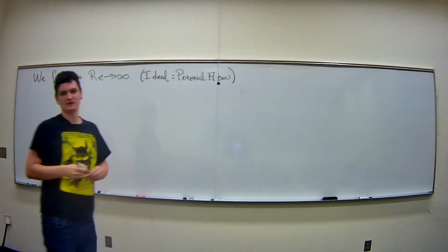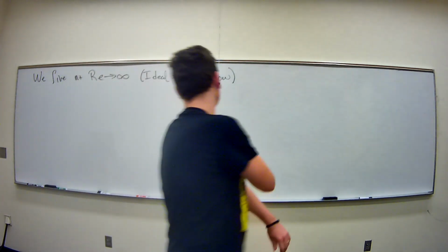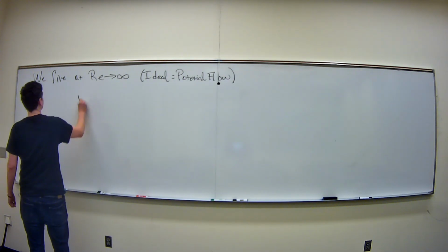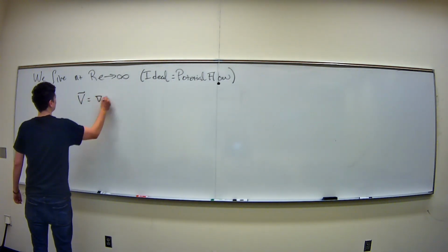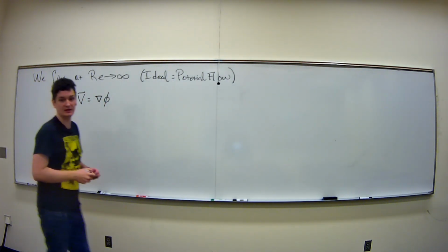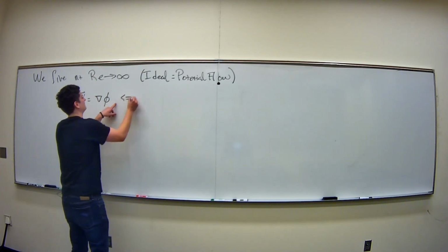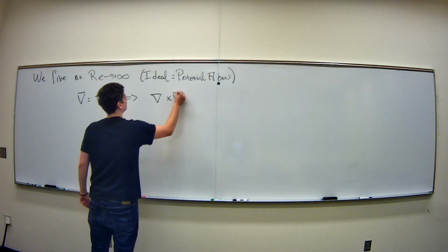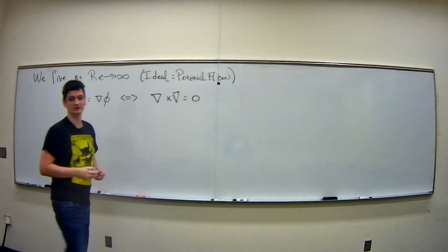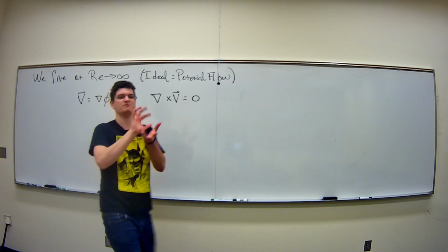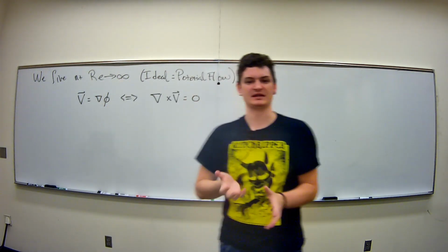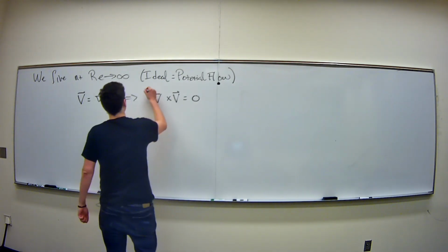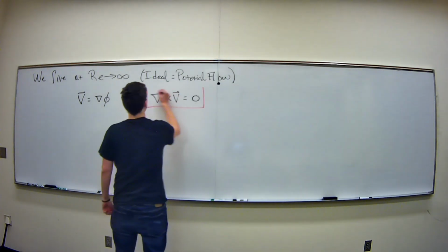Okay, so I don't mean that even actually, right? Because what do potential flows mean? Well, a potential flow was that the solution of this was the gradient of some scalar field. And this is equivalent to this idea that I'm assuming that the velocity field has no curl to it. It's irrotational. There's no mixture of the dimensions happening in the velocity field. And that is the assumption of ideal flow, right? It's a pretty stringent assumption.